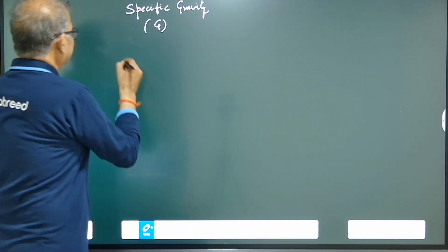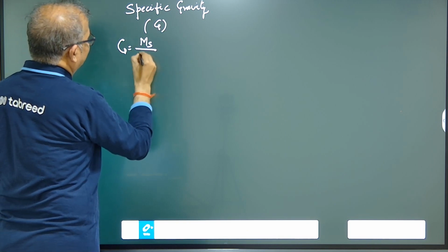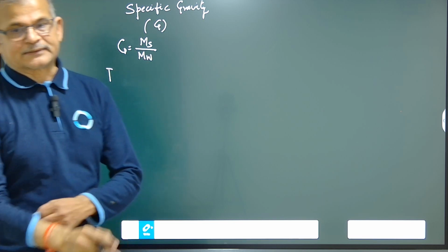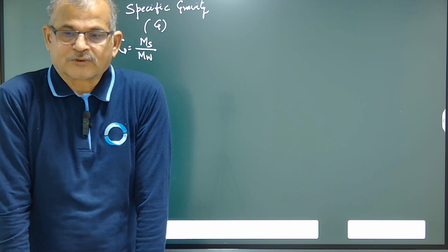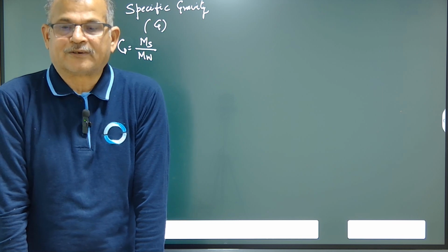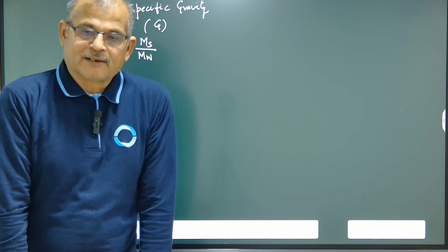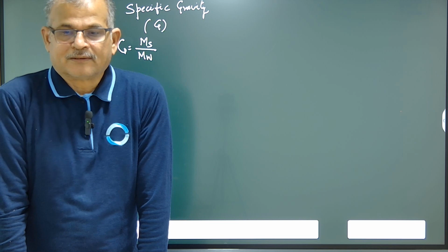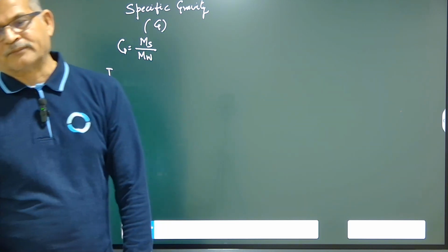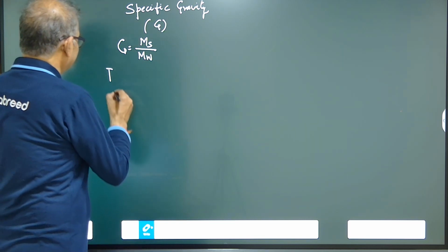We know that specific gravity is the ratio of the mass of soil solids to the mass of an equivalent volume of water. In IS 2720 part 3, a complete procedure and the apparatus required to determine the specific gravity of fine grained soil is given. For coarse grained soil, we use a flask of 500 ml or 250 ml and a pycnometer of 900 ml. The procedure is the same for fine grained and coarse grained. Only the accuracy with the density bottle of 50 ml is more, since its measurement is counted to 3 digits, that is 0.001 gram.